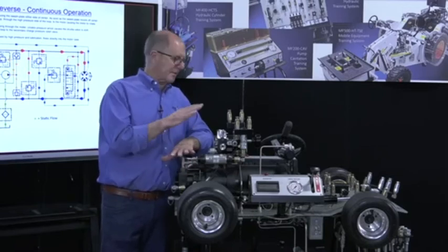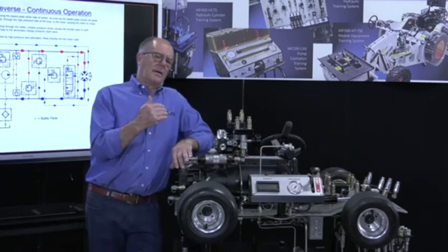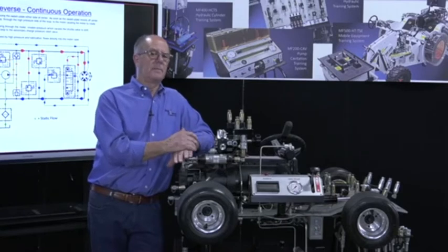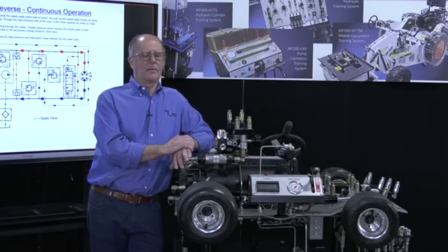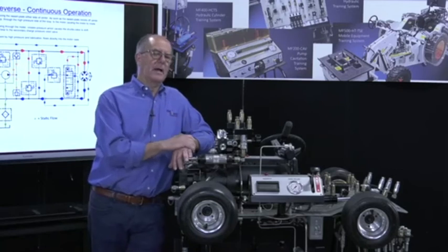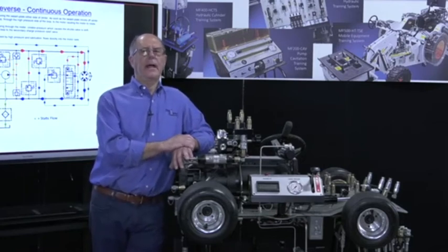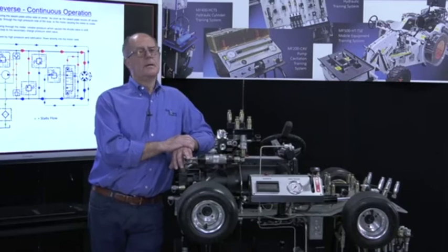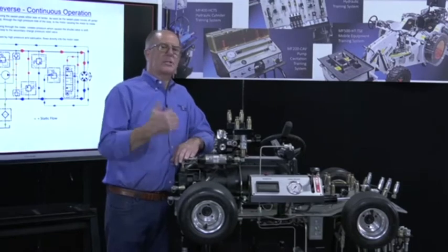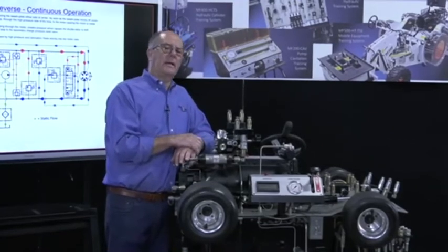Because first and foremost, if you want a filter going in both directions, you have to have 4 filters. There's this myth that if I blow the pump on a catastrophic failure, I'll be able to keep the motor. Well, that's a myth. At the point in time you blew the pump, how did you know that high pressure filter in that line wasn't in bypass momentarily? It was a cold start failure, and I was in bypass. There is no assurance. Second problem, it's halfway, let's say, between the pump and the motor, which means when I start my new system, I'm going to run the oil backwards through a line that is potentially contaminated.